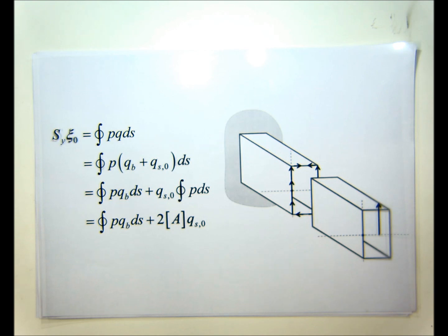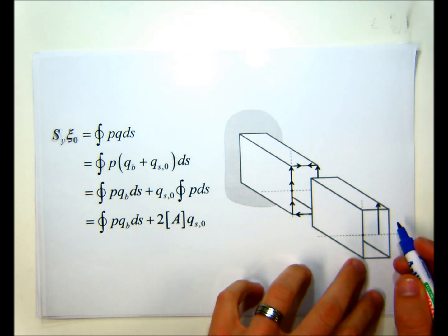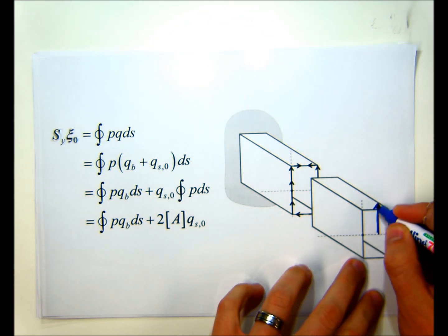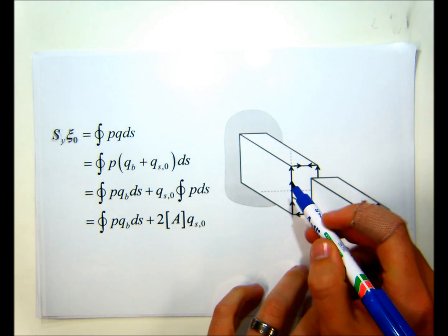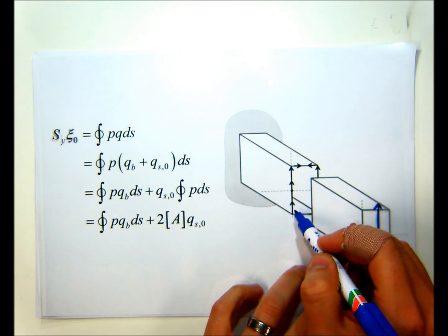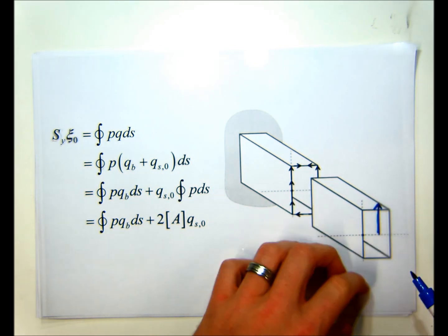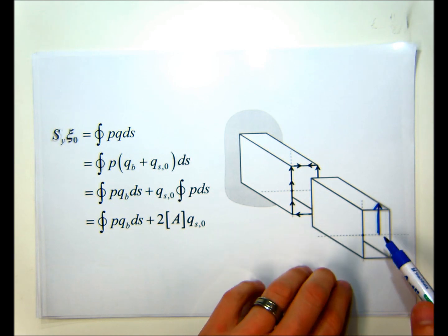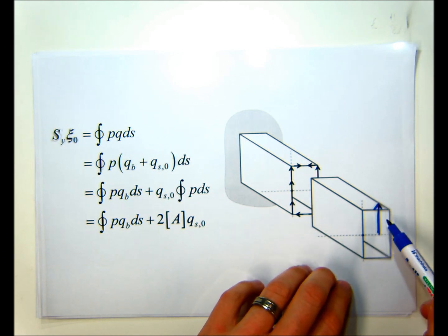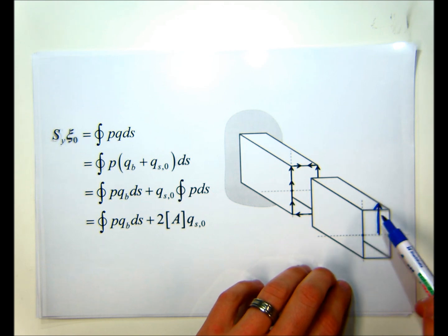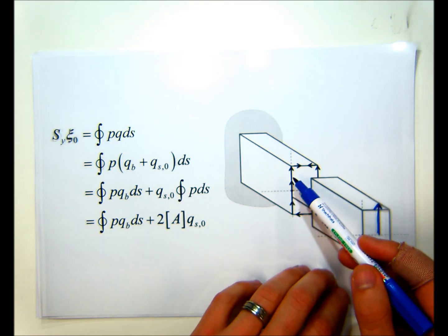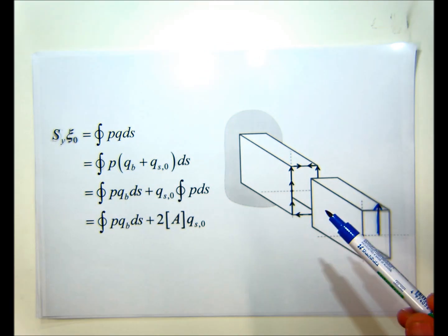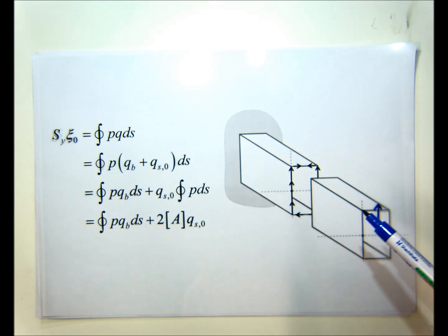To find the constant shear flow, we have to use moment equilibrium in the section. So if we look at our section over here on the right, we have some externally applied load here and some internal shear forces that are set up, or some internal shear flows. Now, based on the principle of equilibrium, we can say that the external shear forces and the internal shear flows on the same cut, the moment of those two should be the same.